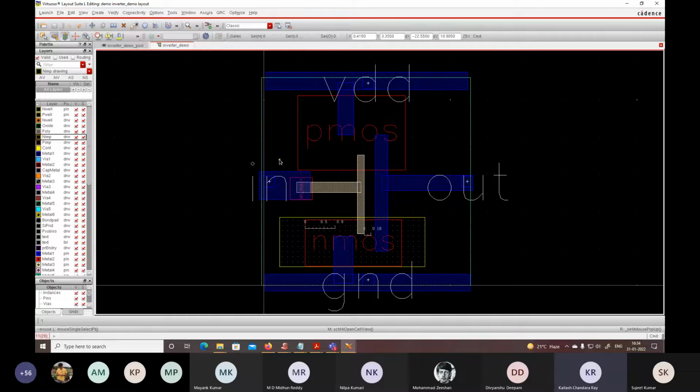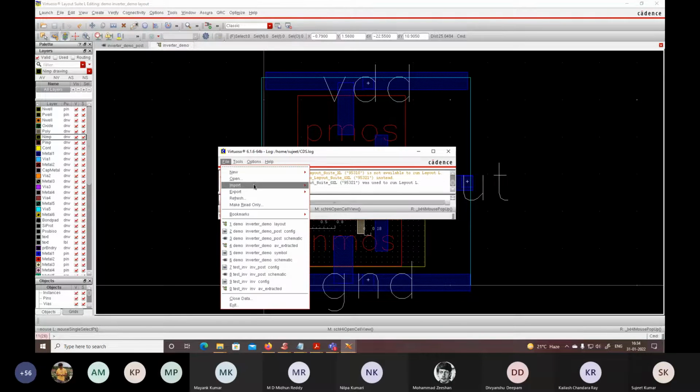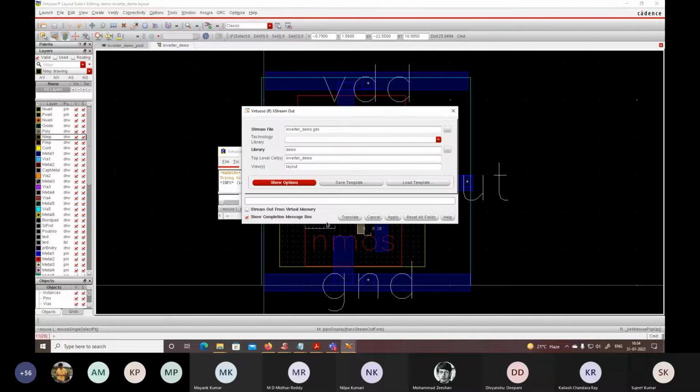Now you export here. So we have to choose the technology library. So we have chosen GPDK 180 nanometer technology here. And in which library we want to export our GDS?